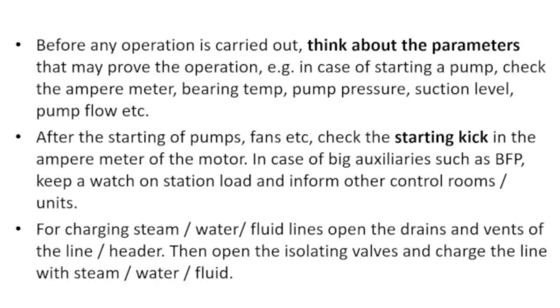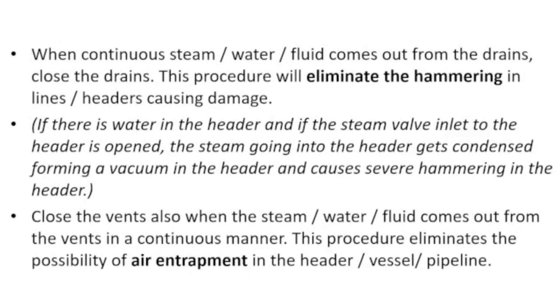For charging steam, water or fluid lines, open the drains and vents of the line or the header. Then open the isolating valves and charge the line or header with steam, water or fluid. When continuous steam, water or fluid comes out from the drains, close the drains. This procedure will eliminate the hammering in the lines or headers causing the damage.